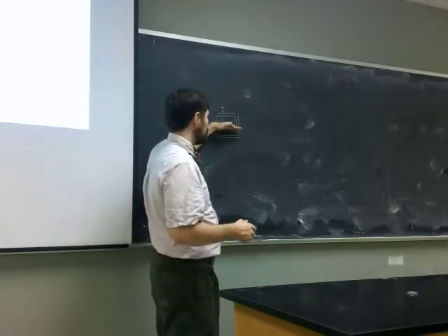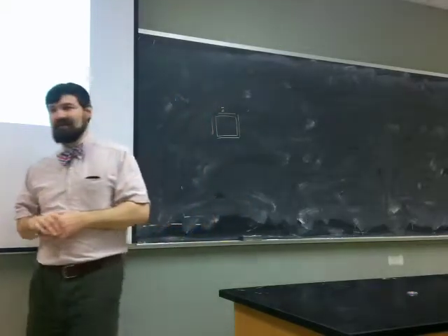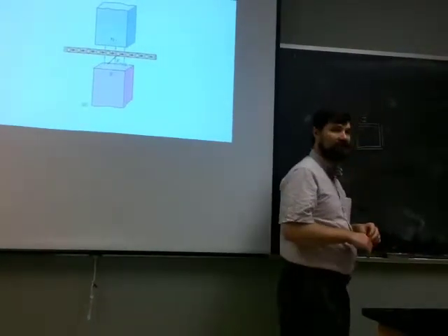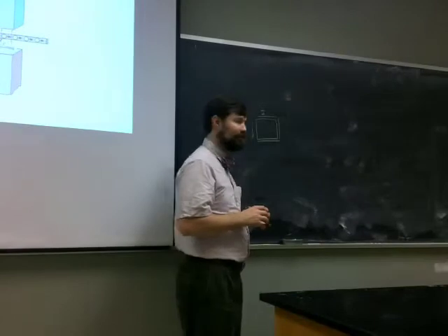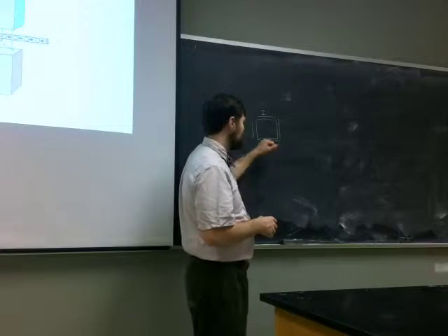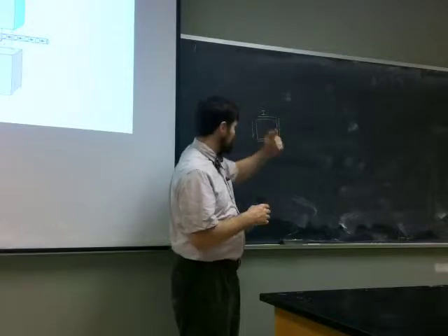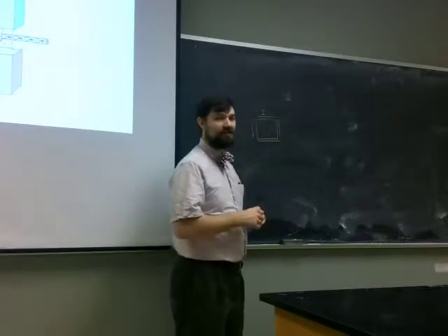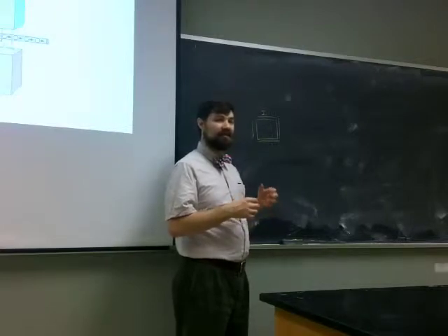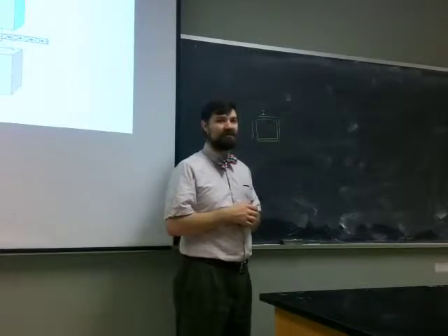But now imagine that this thing is oriented like this, and you've got your two magnets. That means that on one branch, say this one and this one, they're parallel to the magnetic field. No force. The other two are still perpendicular, but now you get a force on one of them that points this way, and on the other one it points this way. So the net amount of force is still zero, but there is a net torque. If there's a net torque, then this thing is going to want to rotate.